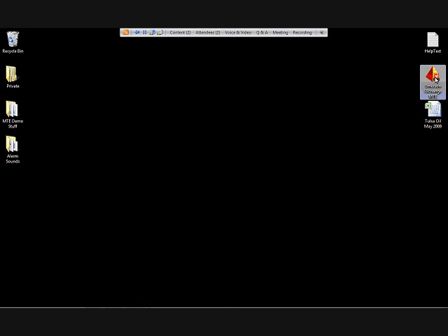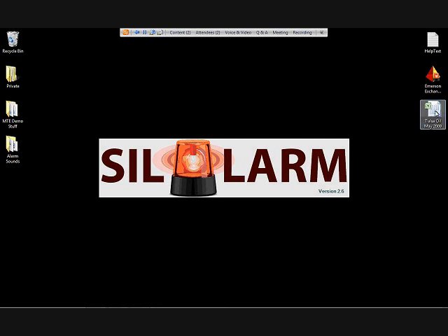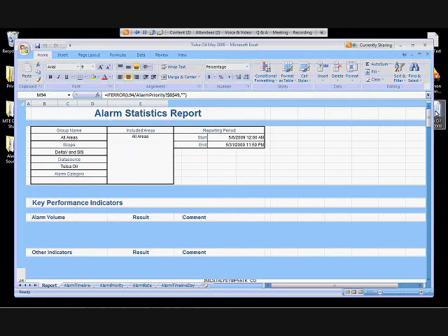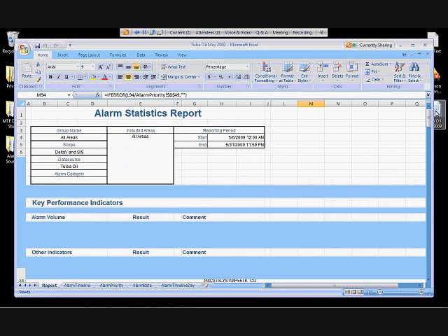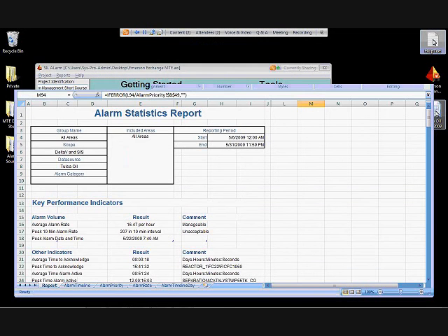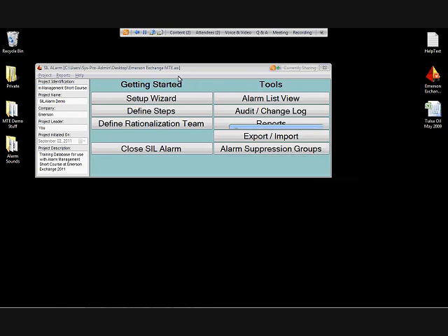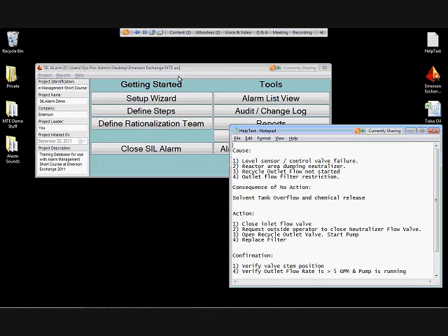Okay, thank you, Kim. While we're getting lined up here, I just wanted to say the DeltaV Analyze tool is great at creating actionable results that we can take care of during the rationalization process. Today, what we're going to focus on is the chattering alarm that was identified in Analyze, but certainly many of those other issues that you pinpointed in Analyze we could address through the rationalization process as well.